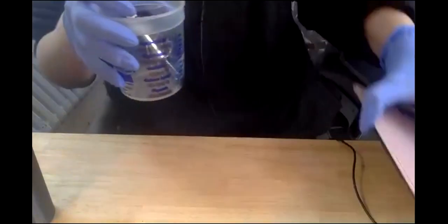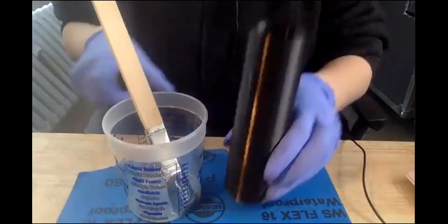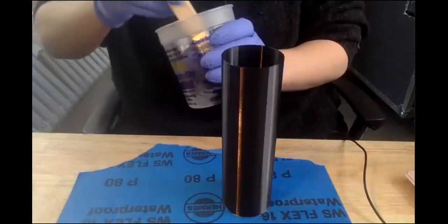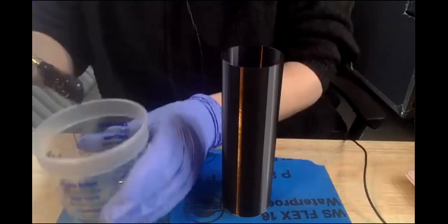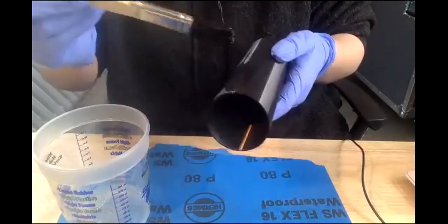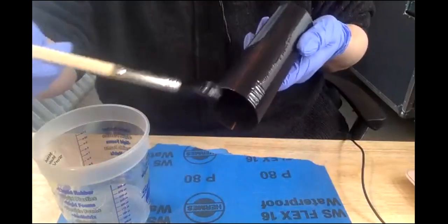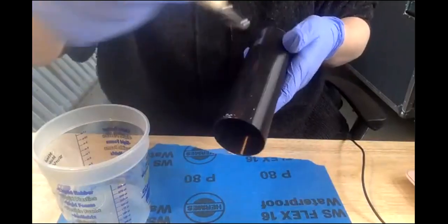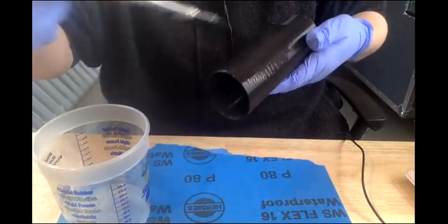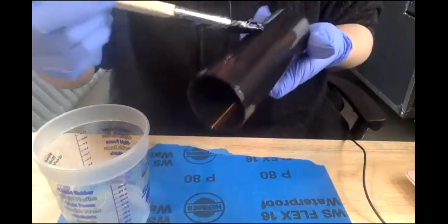Move this aside. I'm going to use this because I didn't really prepare this working space. And then you really simply just brush it on. This is what I wanted to show, just to show how easy this is, because if you want a smooth surface, this is really the first thing I would recommend. So just a really thin layer, like so. You see it's got some brush strokes, but it doesn't take long for them to even out. It doesn't have to be too thick, or else it will sag and drip a little bit if it's super thick.